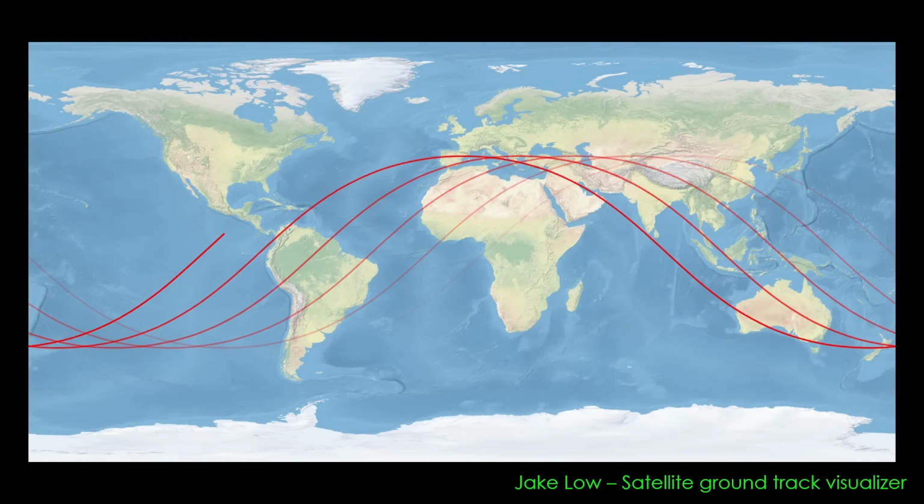Because the Earth is rotating to the east under the satellite, the ground path of the satellite moves westerly with each orbit, so you can merely wait until the satellite ground track is passing over your landing site and choose that orbit for re-entry. That happens roughly twice a day for low Earth orbits, with one when the vehicle is moving towards the north and one when it is moving towards the south, though the ground track over land may make one of those directions less practical. That means that we don't have to consider Droneship landings for our second stage. It can land on land in a convenient location.